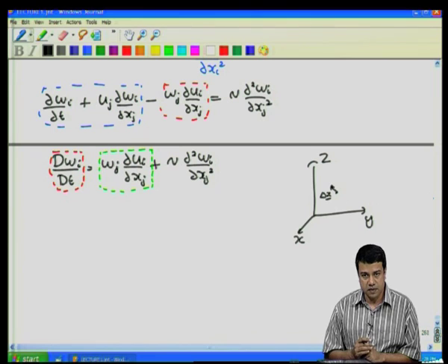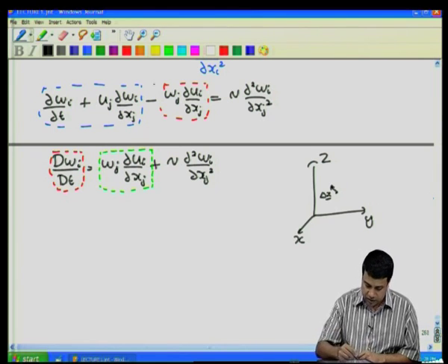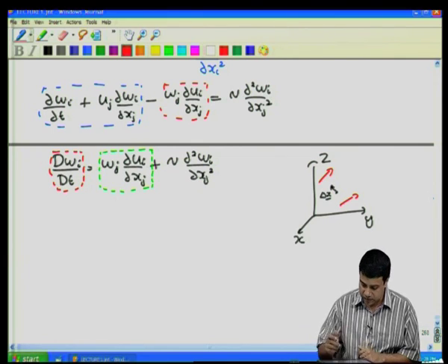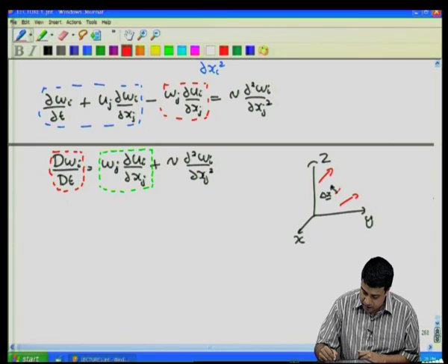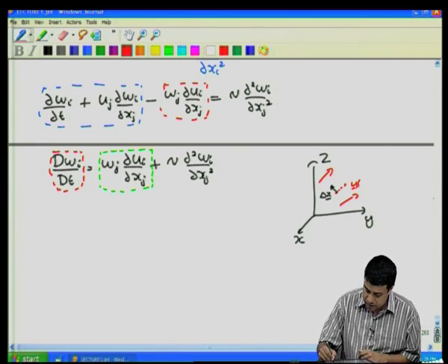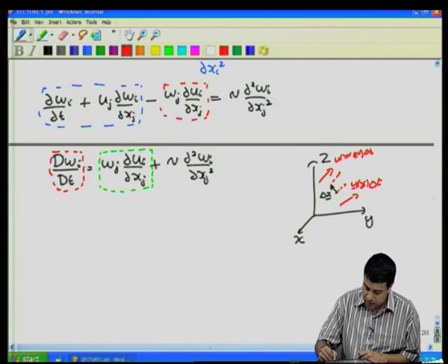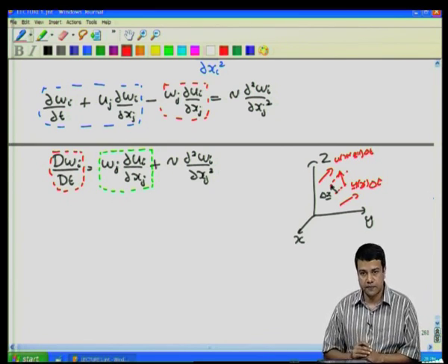As time progresses, because of the fluid flow, this material element is going to stretch and bend. And how does delta x vary due to the fluid flow? You can see that at some later time, this goes to u at x times delta t, this goes to some other location u at x plus delta x times delta t. And you get a new material element.